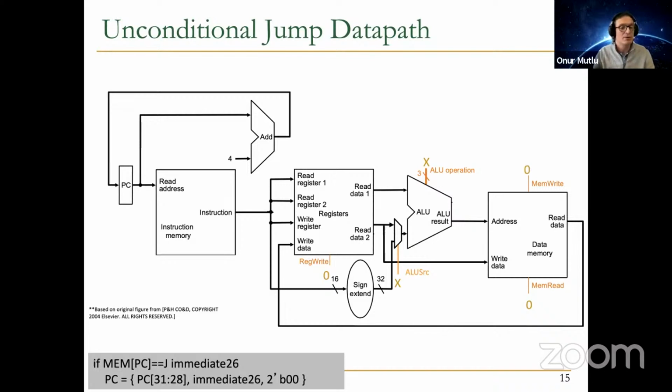In some of the microarchitectures in your book, for example, they omit this mem read signal. They talk about the mem read signal, but having it be 0 could be good, because that way you ensure that you don't access memory, which can save power, save energy, right? If you don't have a mem read signal, you read memory, fine. You get some result, but you ignore it in the end. But that consumes some energy potentially.